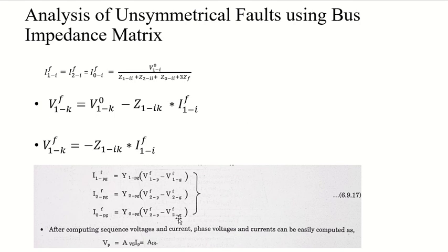And that is also the aim of this fault analysis. That is why we are using this unsymmetrical fault analysis with the bus impedance matrix, so that you can generalize it and use it for all the buses, even for any changes in the power network, right? Because remember, we saw earlier how we can modify our bus impedance matrices.